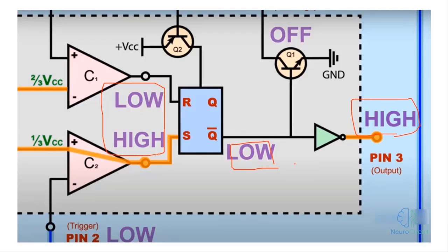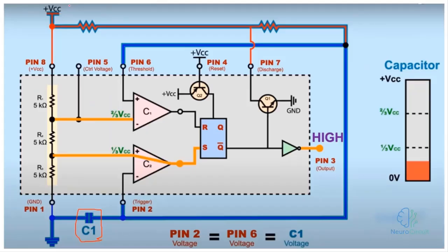As we mentioned in the monostable mode, when the not Q output, or the flip-flop output, or when my flip-flop output is in the low state, the transistor here is in the off state. That transistor connected to pin number 7 here is off, or in other words, pin number 7, which is the discharge pin, is in the off state here, meaning it's turned off. When the transistor is off, you can see this VCC here flows through.